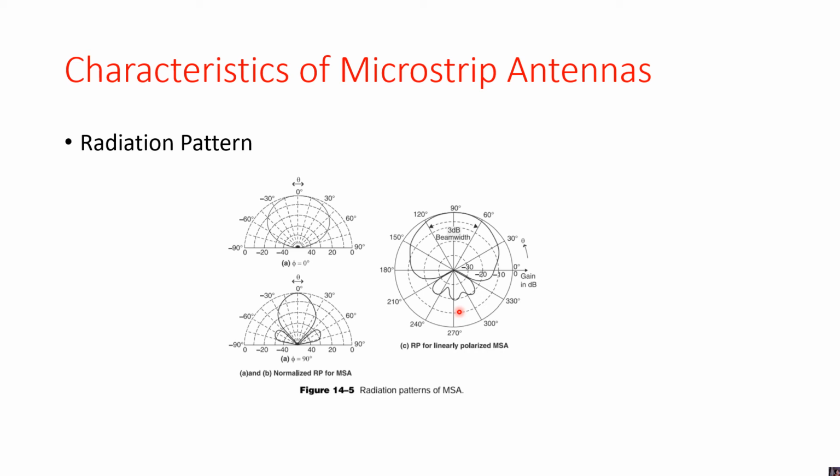Usually when you consider microstrip antennas, the patch is the conductor, so the voltage and current will usually be out of phase. Voltage will be maximum at the end of the patch and minimum at its midpoint, and the field underneath the patch will be like the different fields shown in the figure above, and the fringing field near the surface of the patch will be in the y direction.